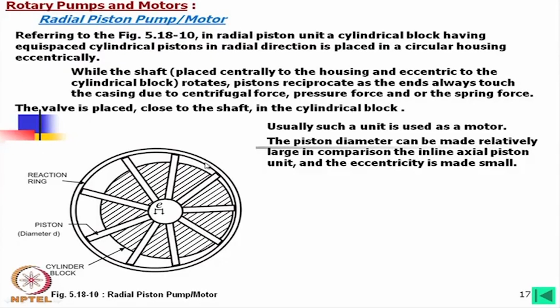pistons, 22. In this case, say if the barrel size is the same, but for all the pistons this angle is not much. In that case, say we have 21 degree. In that case, this angle is not that high, a very small angle. So, reducing the space in between, we can probably use up to 25-28 millimeter pistons. So, we can use very large pistons there, but eccentricity we cannot make very high. That means the stroke length will be very small.